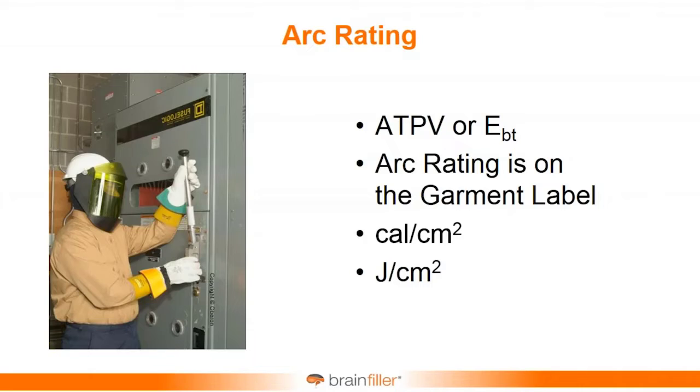Globally, some have opted or pushed towards joules per square centimeter. In fact, NFPA 70E used to use this, and then in 2018, they reverted back to calories per square centimeter as the primary units. And some, particularly in Europe, have actually labeled PPE based on kilojoules per square meter, which is an interesting number when you go through the conversion.